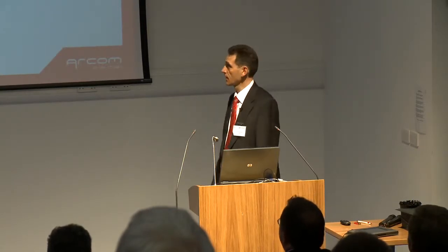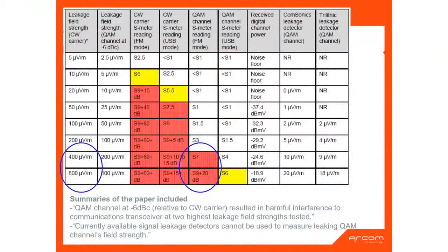So in 2009, Ron Ranach and Ray Thomas were testing what influence of the leaking QAM channels they may expect on transmission in the aeronautical band. They were using their spectrum analyzer, a QAM channel source, and a ham transceiver for checking what is going on in the 2-meter band. This is a chart from their paper. What we see here are the results of their test.